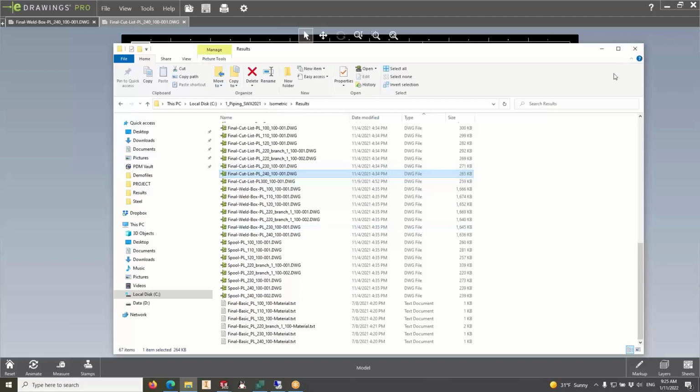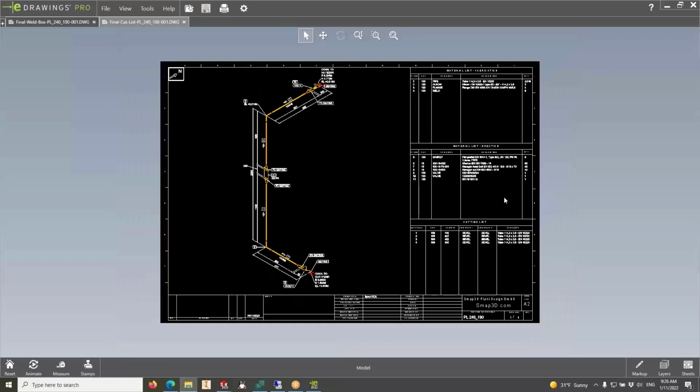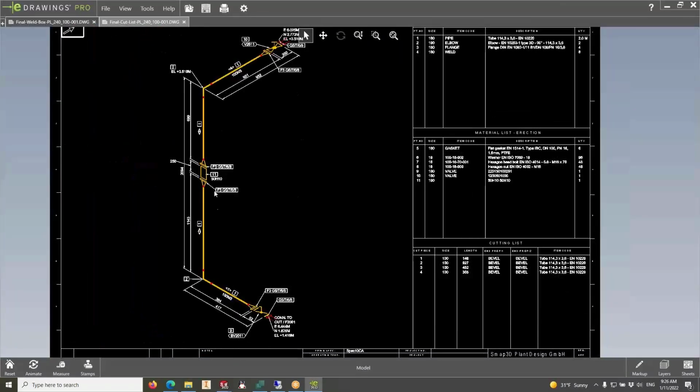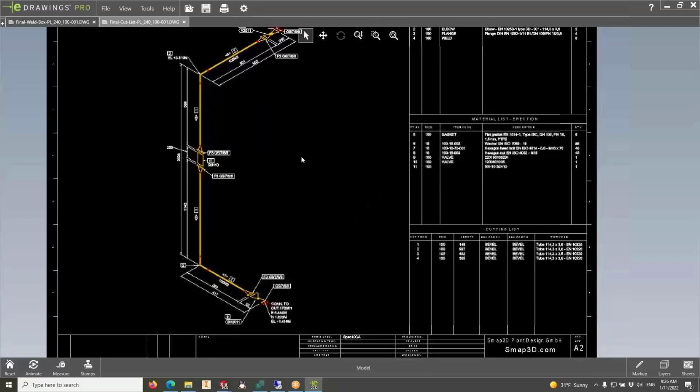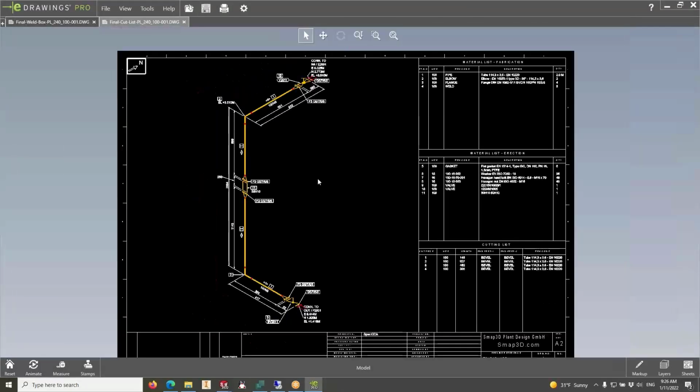And so that's really our process of going from P&ID all the way into SolidWorks, doing the 3D layout in SolidWorks, and then being able to choose whether or not we want to use SolidWorks drawings because they're easier for non-pipe fitters to read, or whether our audience is the pipe fitters and they're requiring these isogen drawings, which are much faster to generate instead of having to manually do everything in SolidWorks.